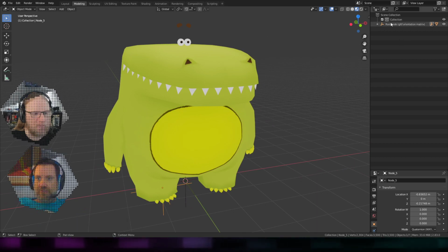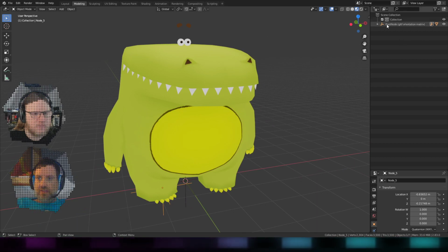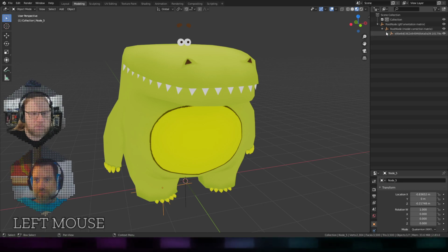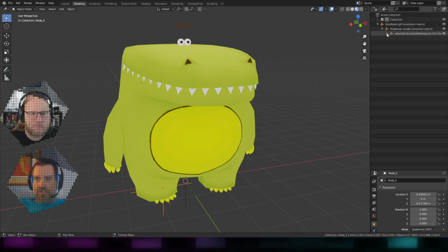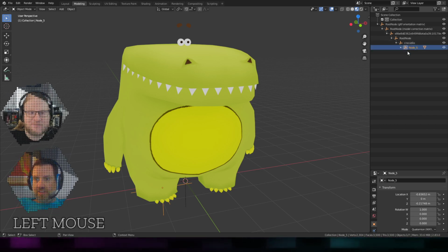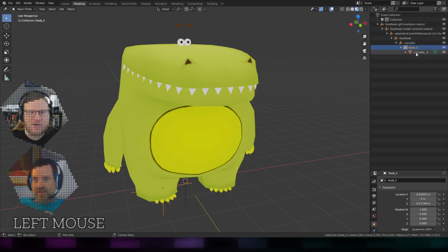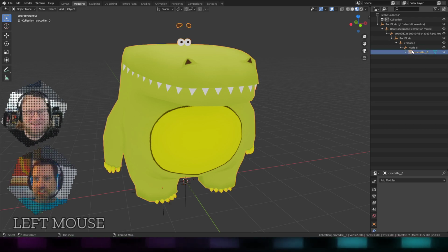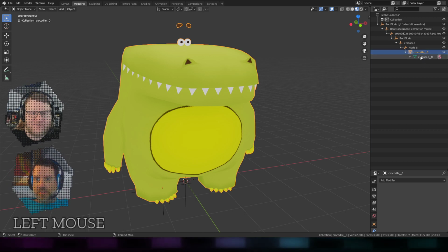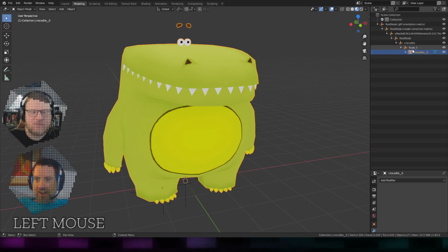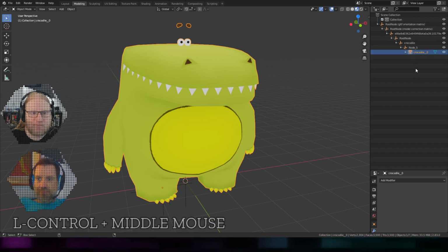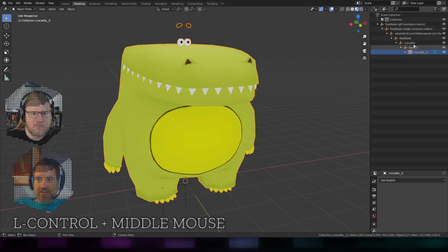So if I look over in the hierarchy here, it starts off with this root node, and then there's another root node, and then a long string of garbage. I don't know what that is, and then another root node. So basically, I'm looking for the actual model. There's the actual model. It looks like a little inverted orangish triangle, and then the mesh underneath that. So all I really care about is that one. All this extra garbage above it, I can just get rid of.